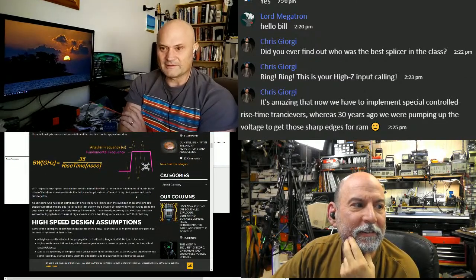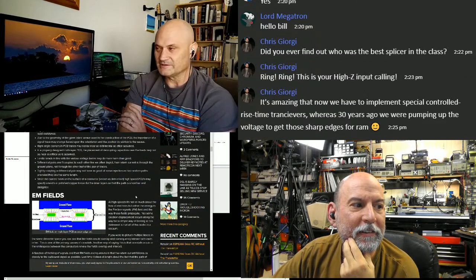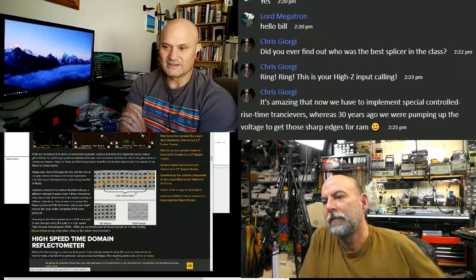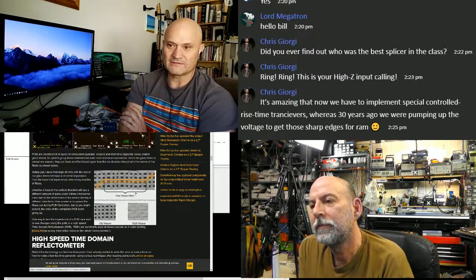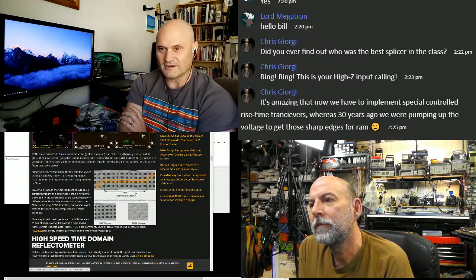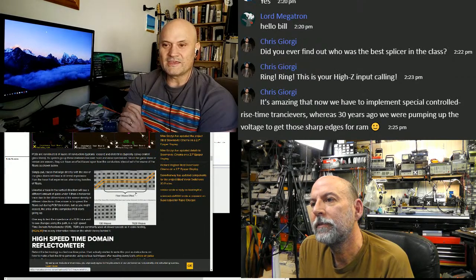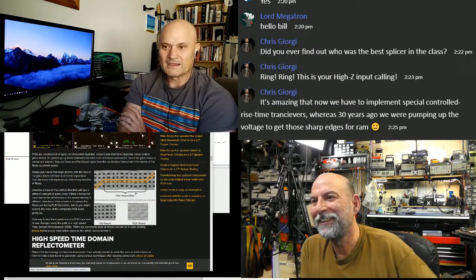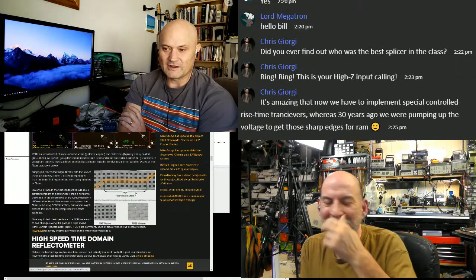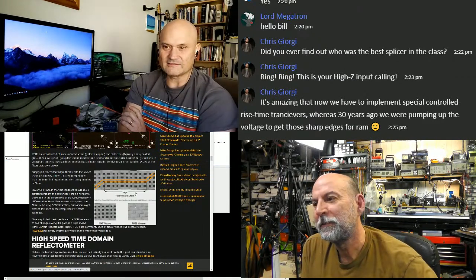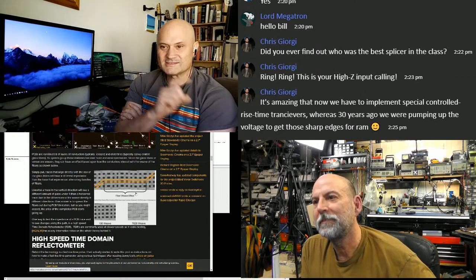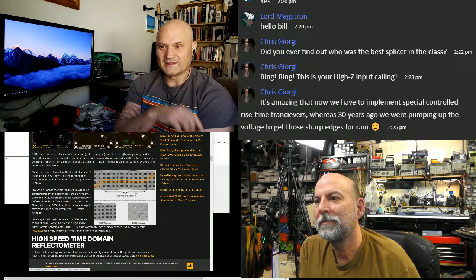So this is something Rick Hartley talks about that I really enjoyed. It was an existing product in the market for years, no problem, passed EMI, FCC certified. Then the Texas Instruments or whoever it was that made some of the logic chips changed them, did a die shrink. I said, it's a drop in. It's exactly the same part number, same order number. Suddenly, this company's products were failing EMI testing.